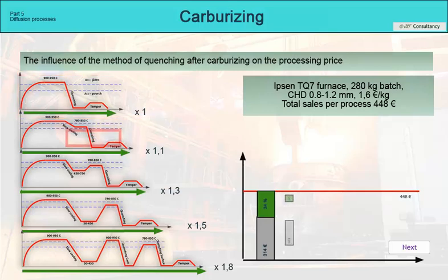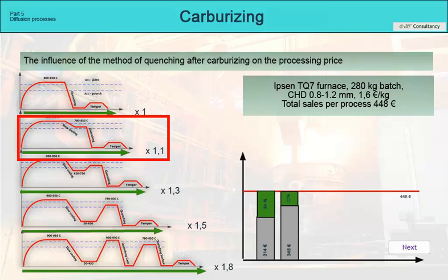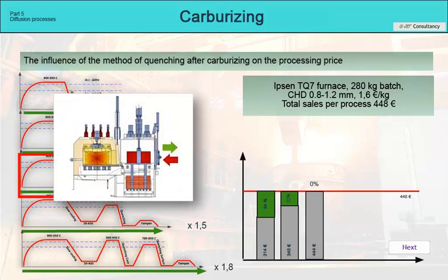Another option is to cool to a quenching temperature corresponding to the amount of carbon in the layer, namely 780 to 850 degrees Celsius. Although this option is usually 10% longer in time, we still have a good profitability of the process. Option 3 will be valid for a single-sided chamber. In this case, after carburizing, we transfer the batch to a cold chamber.